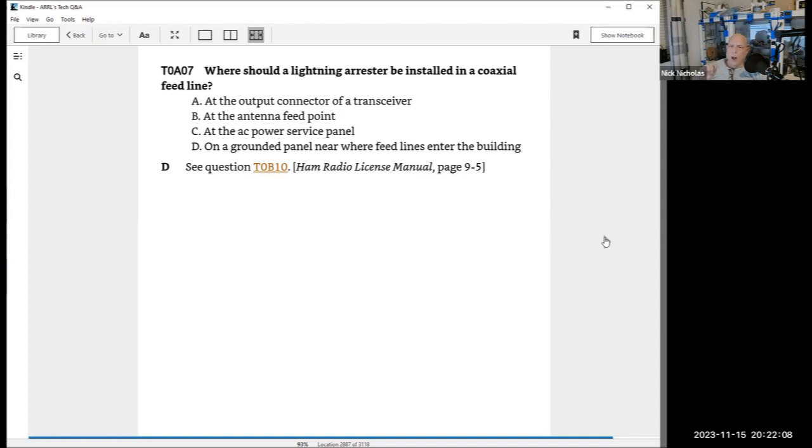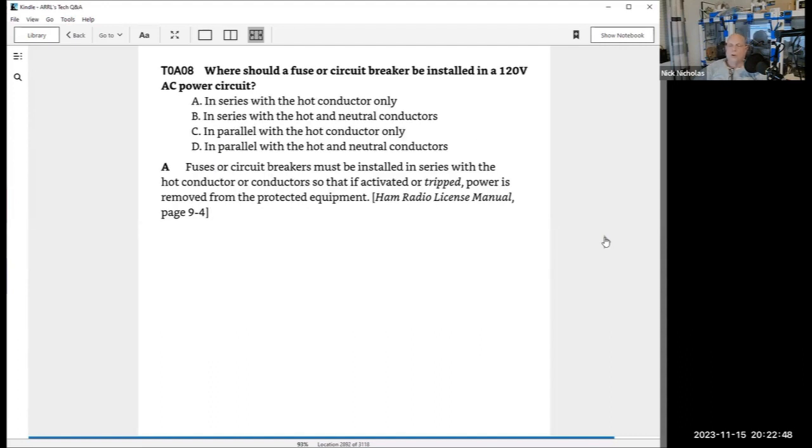You want a lightning ground arrestor. You want that lightning arrestor tied to ground so that it removes the static buildup or charge, minimizing the chances of a lightning strike. It does not prevent a lightning strike. It will not redirect a lightning strike. It will not protect you from a direct lightning strike. But lightning wants to go not to the most neutral point or ground. It wants to go to the highest oppositely charged location. By dissipating any charge through a lightning arrestor, you won't make your location the place it wants to go. That's the theory, and it generally works.